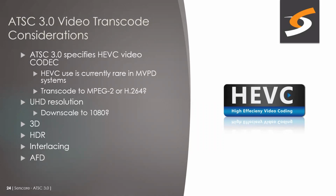AFD is another one. The ATSC 3.0 signal does include an AFD mechanism in it. So the format, active format descriptor, how to change from widescreen to 4:3. Certainly a transcoder would be able to follow any AFD that's in the 3.0 if it's doing a widescreen to 4:3 conversion, or maybe even preserving that AFD into the signal afterwards. So certainly some consideration has to be given there as well.